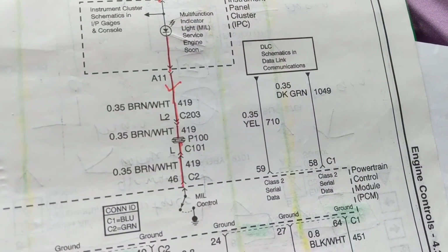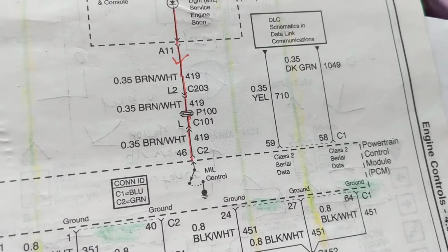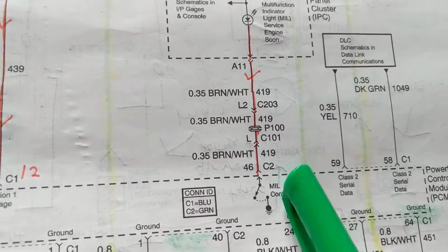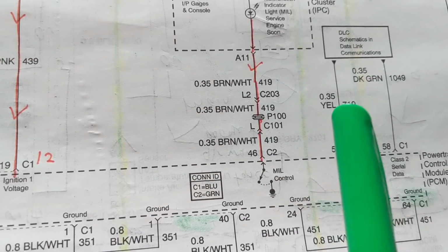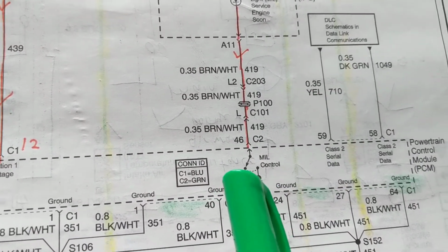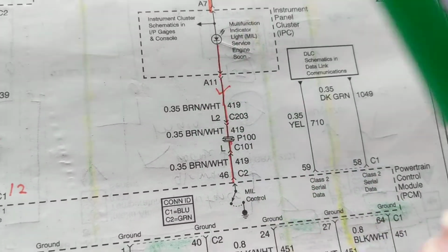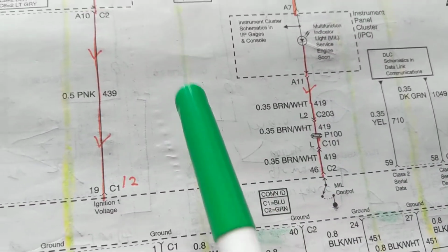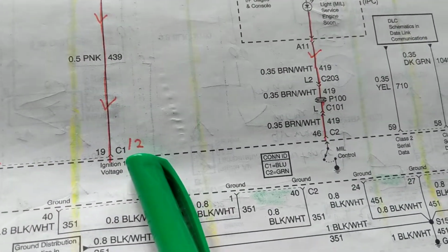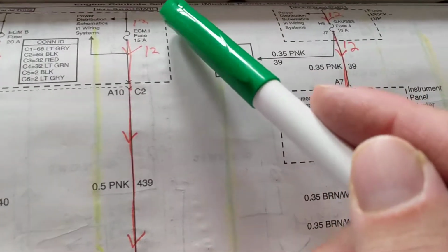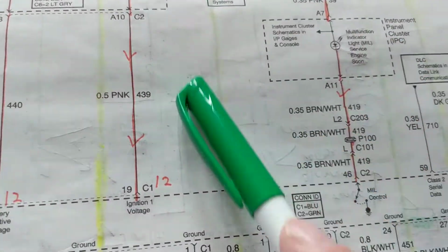The problem is, check engine light goes on. That's okay. It's supposed to go on. Why? I started off this video and I said, sometimes it could be for good. Well, the fact that the check engine light comes on as a self-test tells us what? Tells us that this has 12 volts. The computer is getting its 12 volts. That's good. That means the fuse, which is ECM1 fuse, is operating.